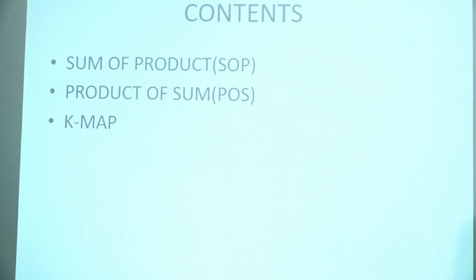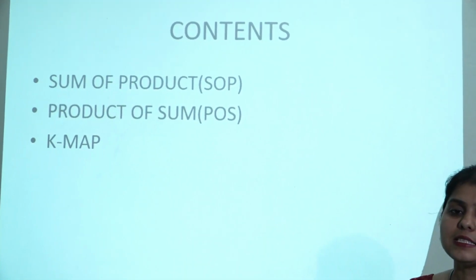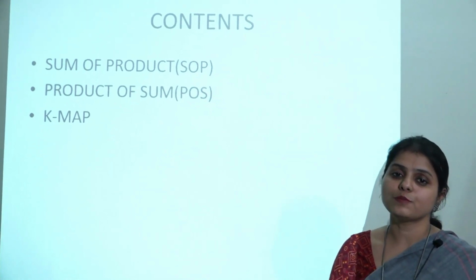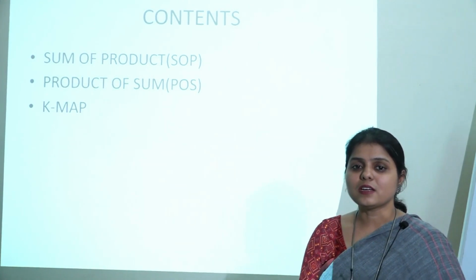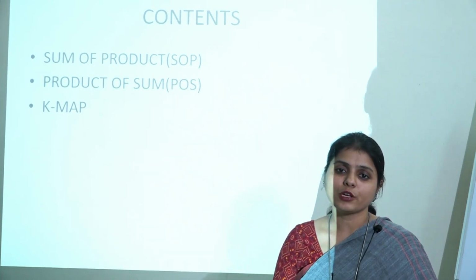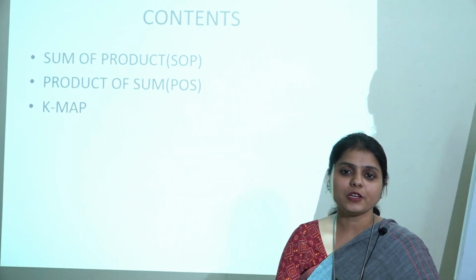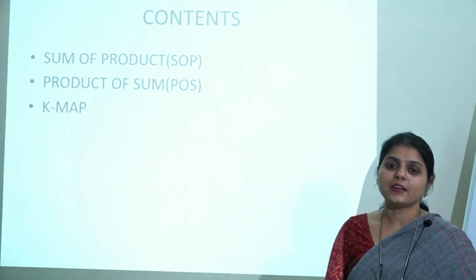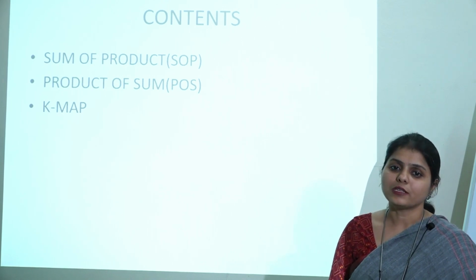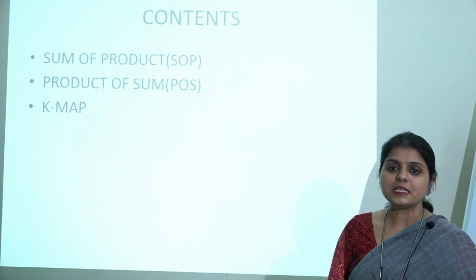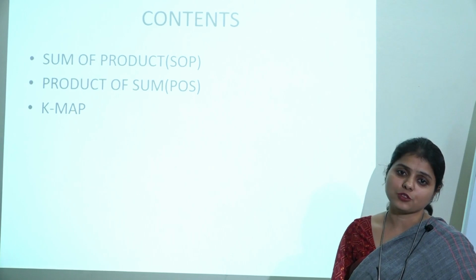So today in the session we are going to cover these three topics. One is sum of products, second is product of sums, and the third one, the most important concept of digital circuits, which is K-maps. In the last class we saw there are three most important operations that we have to look into to design any digital logic circuits using Boolean algebra. That is the inversion operation or the complement operation, the AND operation or the multiplication operation, and the last one is the OR or the addition operation. Using these three operations we are going to design digital logic circuits.